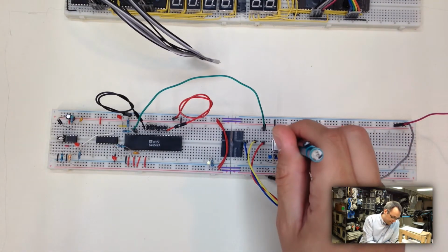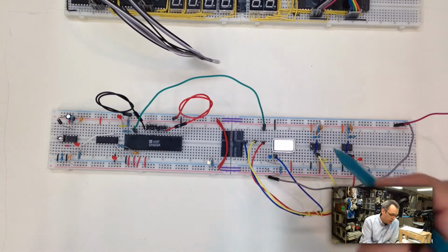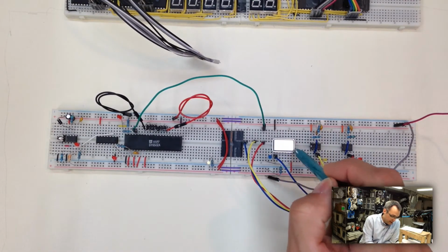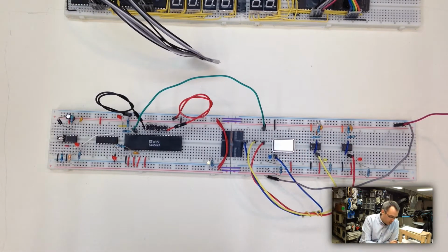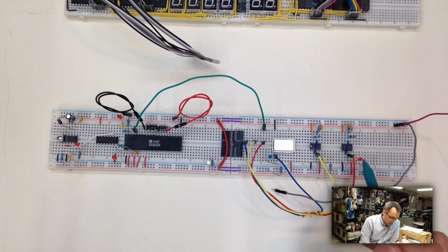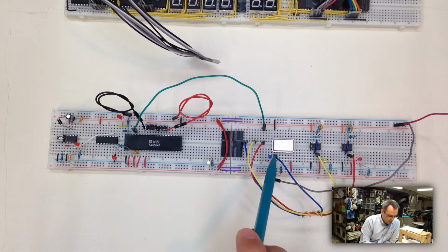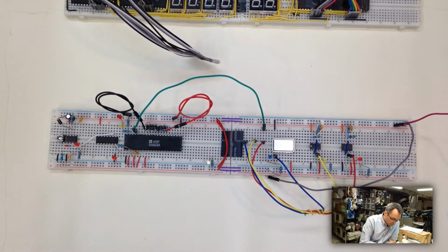And the final oscillator is going to be our final oscillator when we're done, I believe. I don't know, I might change my mind later. This is a 1 megahertz crystal can. Basically, it's a self-contained oscillator. You give it positive and negative, and it gives you a 1 megahertz square wave out. Again, I have it connected to a light just like these other two, so we can see what it's doing. Now this one you can see blink pretty obviously. It's just like on, off, on, off. But this one here and this one here, because these oscillate so fast, the light just looks like it's on. You can't really see it blinking.